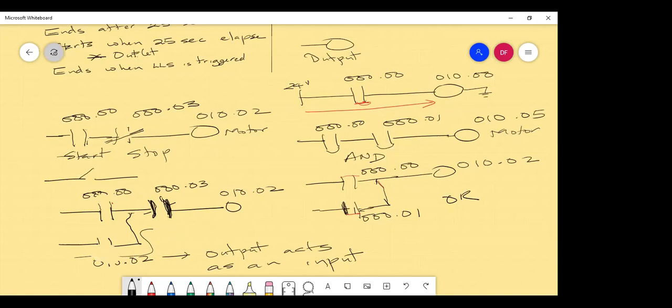And when the two of them turn off, then what is going to happen is that you're going to have 0. Everything is going to turn off. The only way it's going to turn on back is if I push back the switch here and close back the switch here. So the latch, when we have the program like this, this is called a latch, and this is the programming construct that we use.